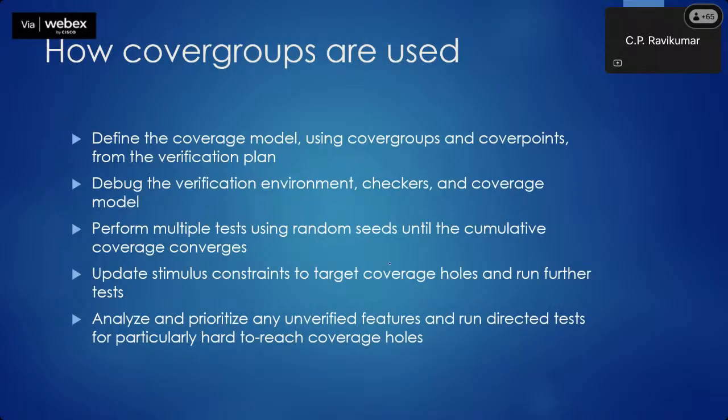See, the system is quite complicated. Whatever system on chip that people are designing is huge and it has a lot of different modes of operation. So you cannot decide that I'll only do directed tests. That will increase the number of months that you have to spend on verification. So they tried to change this by using constraint random testing.